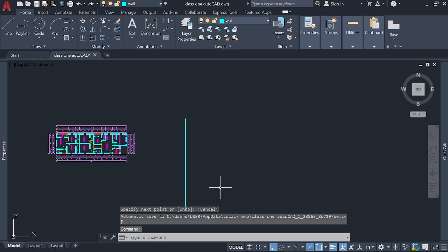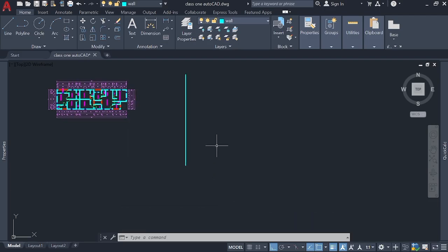Very simple, right? So next up is the what? This line falls under the Home, under the draw tools. These are draw tools. If you check, there are more tools in the drawing section. We have the modify tools. Now I want to modify my drawing by offsetting the line. Offsetting the line simply means creating a line parallel to the existing line using a given distance.